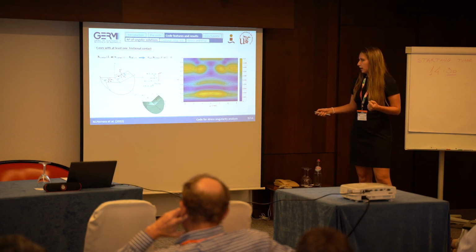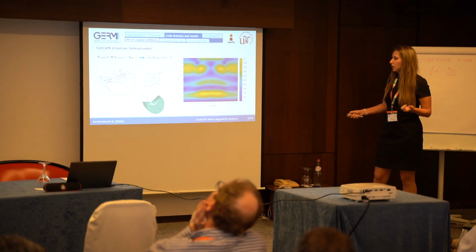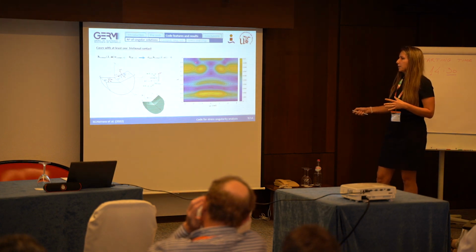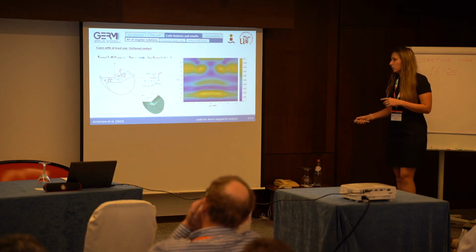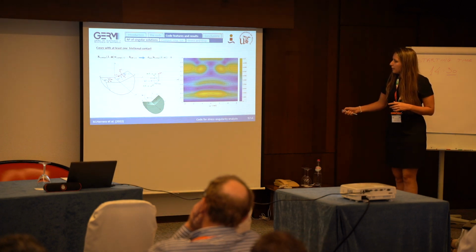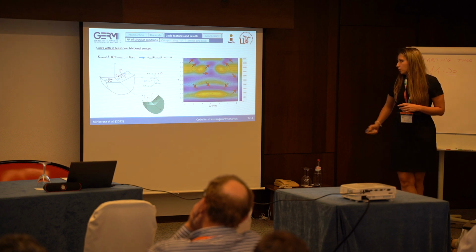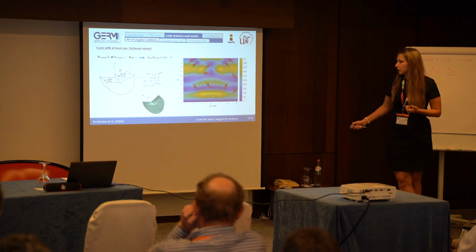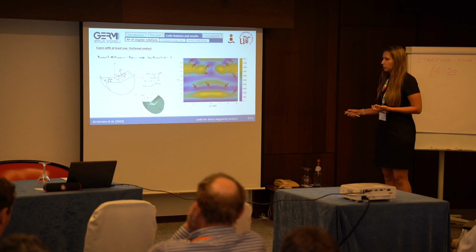As it depends on lambda and omega, the slide parameter that I mentioned before, when there is friction we have to draw a map with the values of the sigma of the singular value decomposition versus lambda and omega, and we will find in the darker regions, where the value of sigma is lower, the possible solutions. In this case, a 300-degree corner with a frictional boundary in θ0 and clamped in θ1, we have 11 possible solutions.